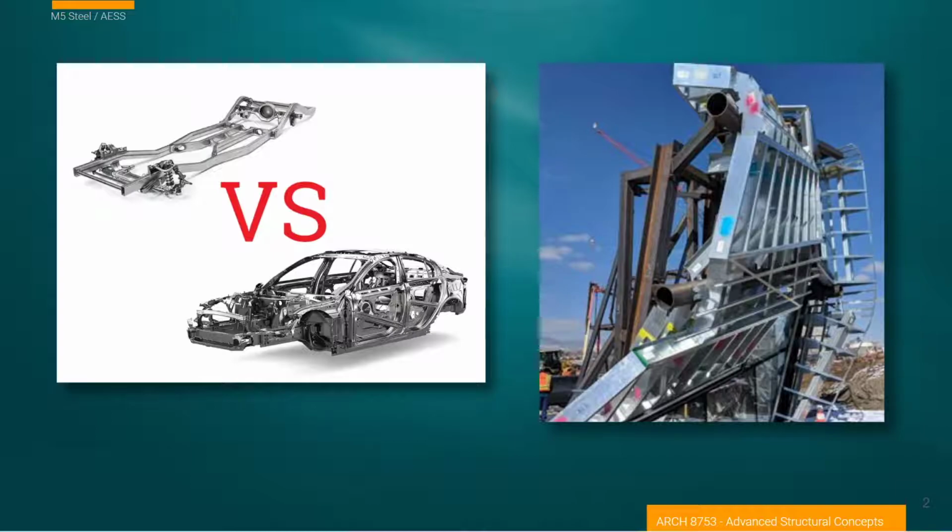Well, today we no longer make automobiles that way. We make what's called a unibody construction, which means that the whole automobile is considered as part of the structural components that give structure to the vehicle. So there are some really important advantages to that. One is that these actually perform better. They reduce the amount of weight that's needed because now there isn't this underlying structure.